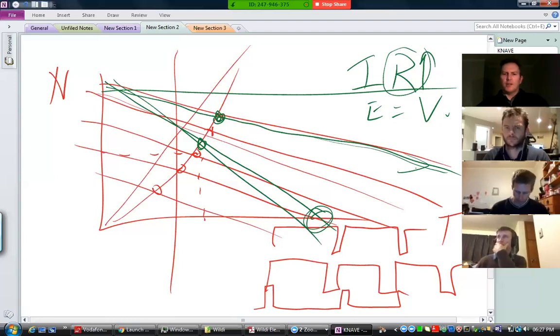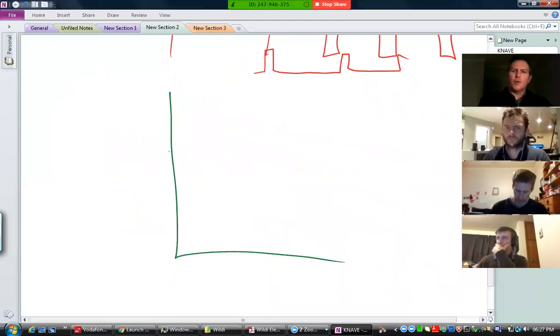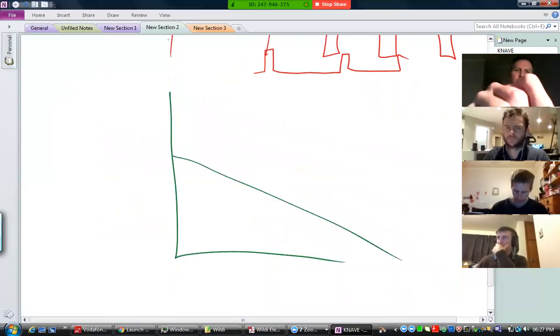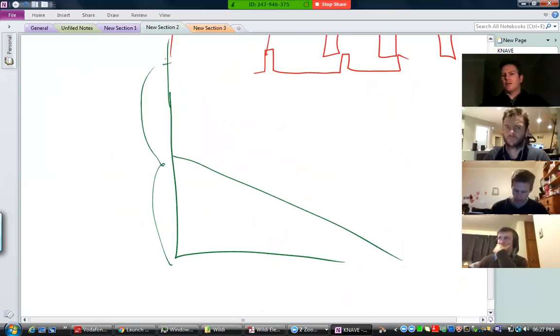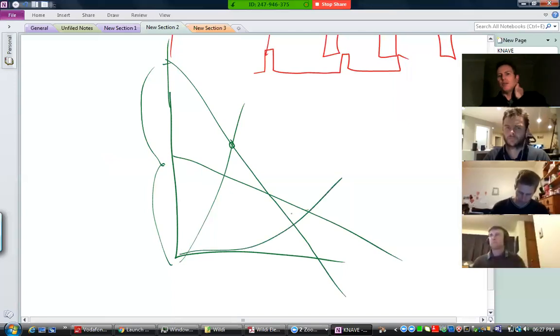The other method is when you weaken the flux. That was your normal graph. When you weaken the flux, this thing becomes twice as high if you halve it, for example, but the graph actually gets steeper as well. I'm trying to think what the reason was. Anyway, it depends where the load is. Sometimes you could intersect and actually be operating faster, but if you have a high torque you could end up operating slower, depending on which side of this point you intercept. But that's a bit of detail we don't really need.